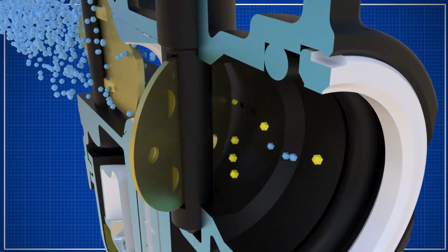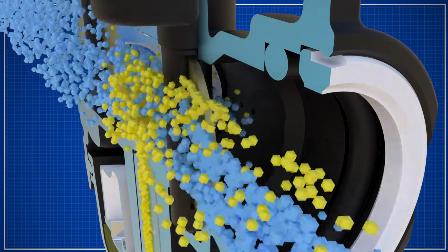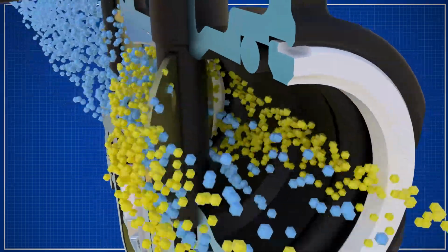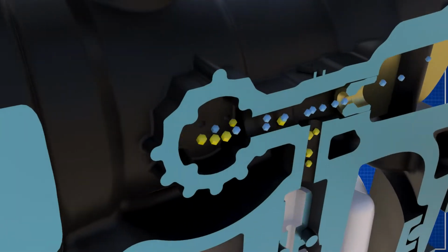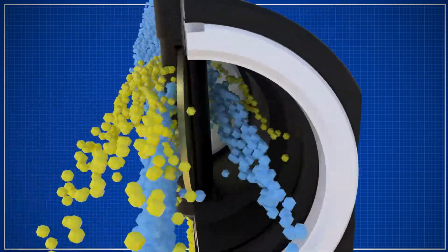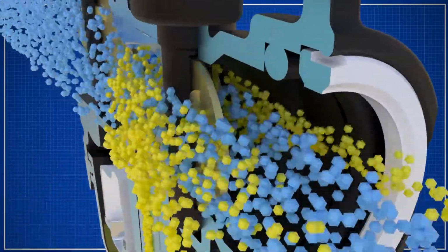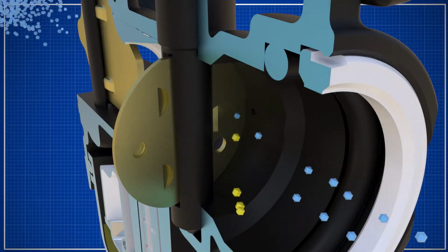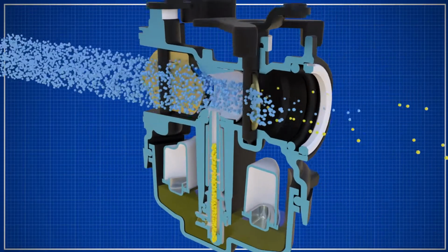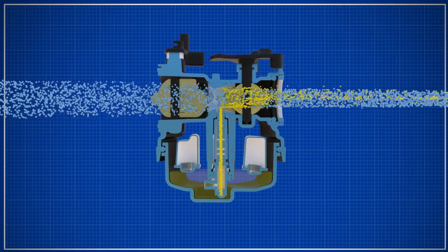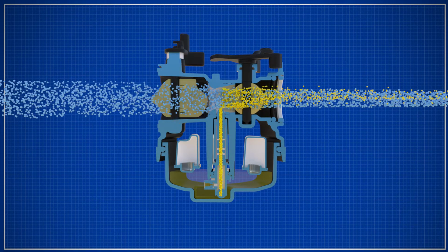Engine speed is controlled by the amount of airflow that goes into the engine through the carburetor body. The carburetor also has internal systems that let it operate at low speeds. It also allows it to operate at high speeds and tolerate transitions between these speeds. Frequently, the carburetor will also have a choke or primer type of system that lets the engine start easier.